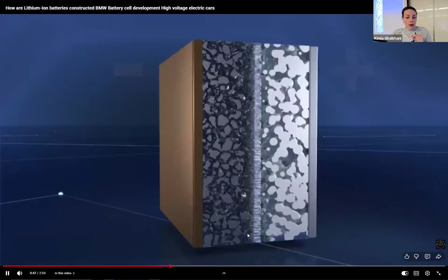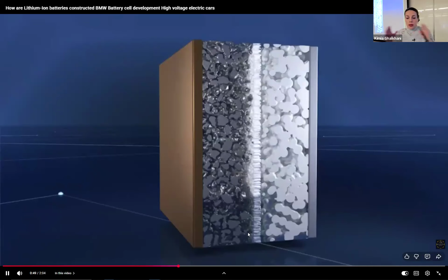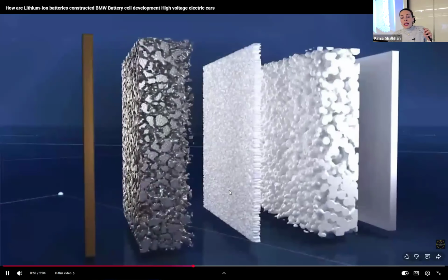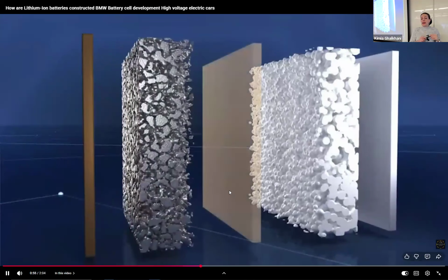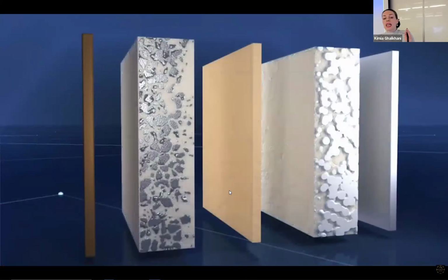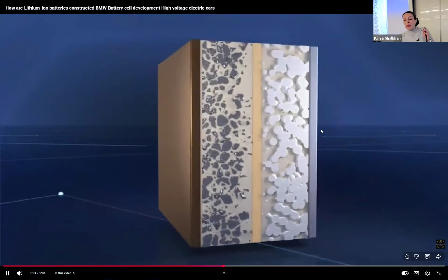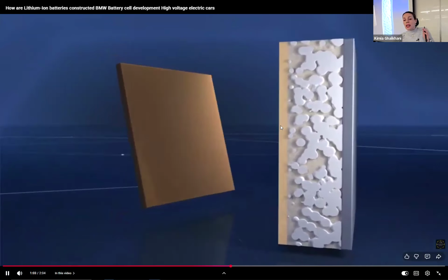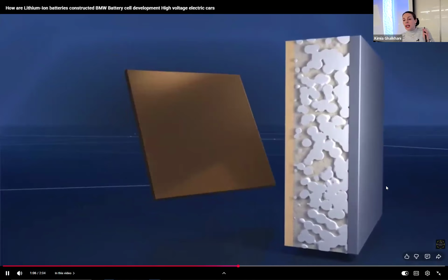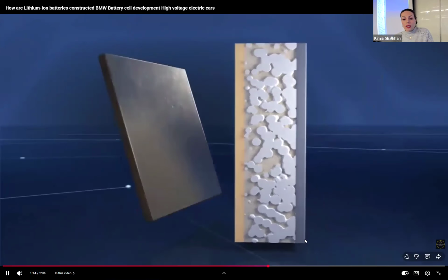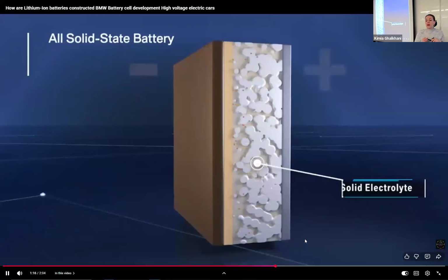In the next part of this video, you can see them separated from each other. Look at here. For a structure of lithium-ion battery, we can have many layers of these separators. For example, this is only one single cell. Beside this, we can add again electrode, again separator, again another electrode, which might be positive. So this is super important to have this understanding of the construction of the battery.